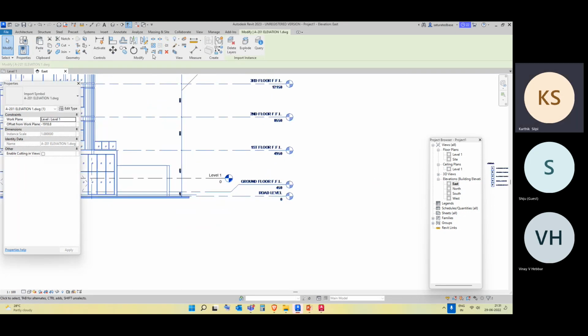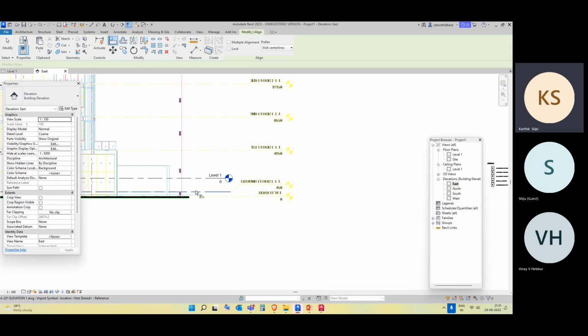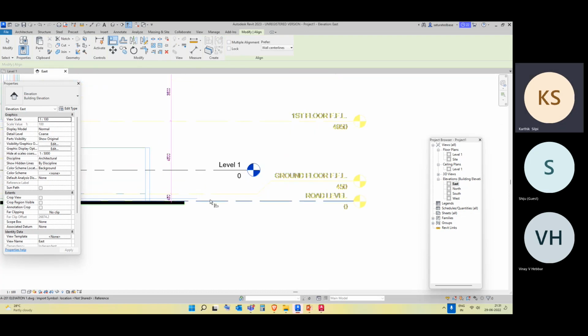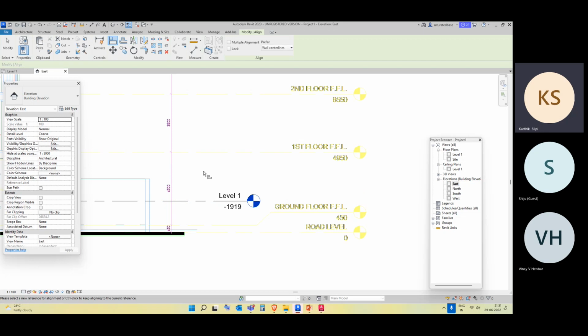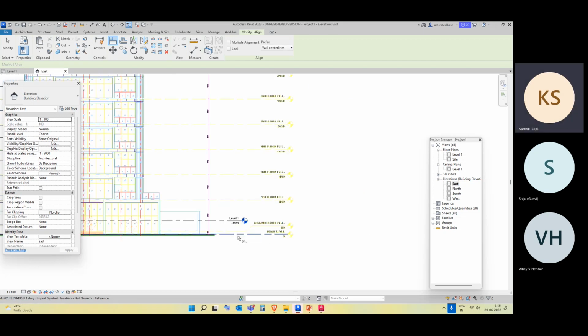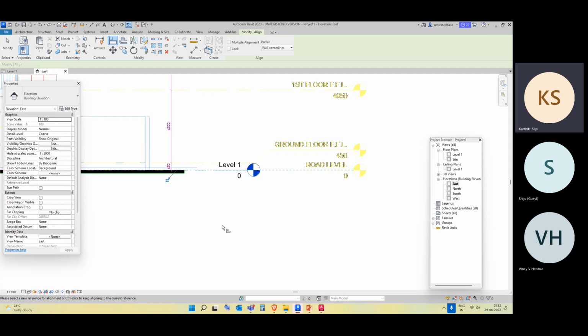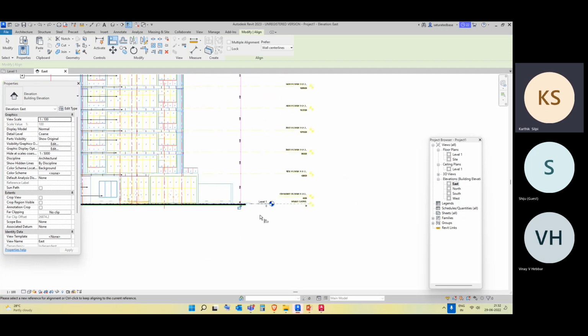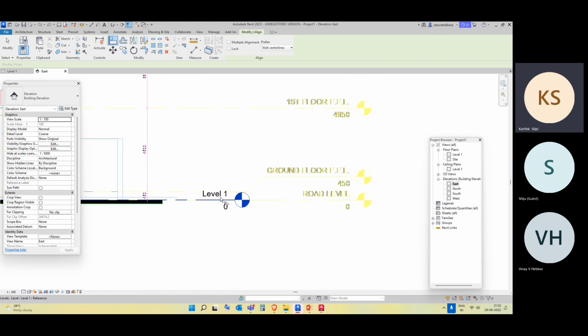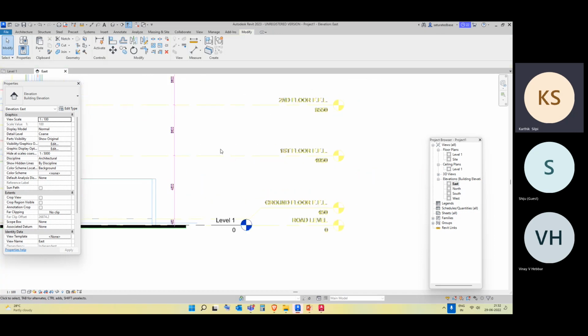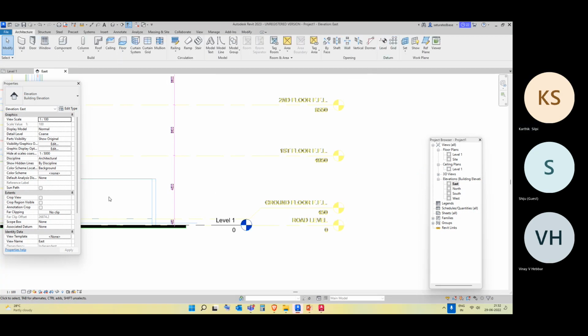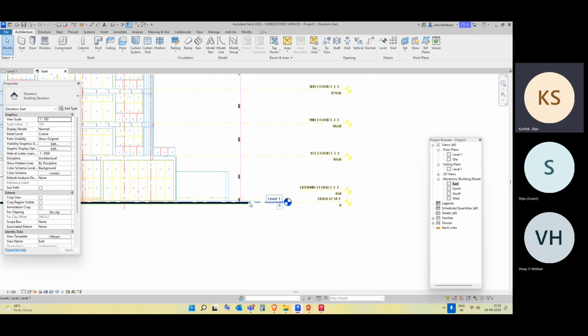You have to select this align command. AL is the align command, or you can select align over here. This has to align over this, so select this point to this point. Sorry, it's reverse. This point, so it will be aligned. Now we have the first level. Based on this level, we are going to create multiple levels. All the levels can be created from the datum section, right? So this is a reference project.